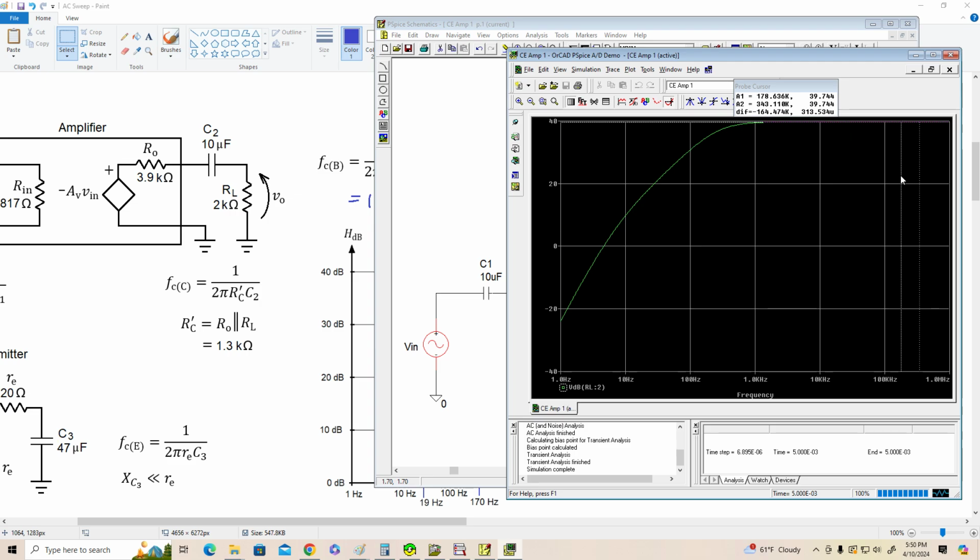So let me start dragging that, and you'll see we're right now about negative 1.1 dB. Keep going, negative 1.8, 2.3, 5, 7, 8, and right about there we're at minus 3 dB, and the frequency is about 256 Hertz.